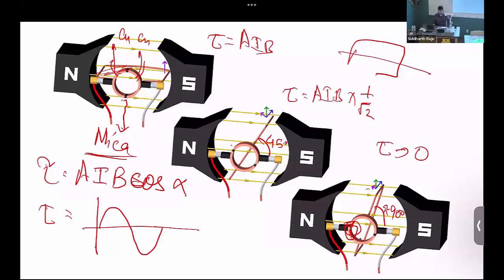So this torque profile, the way I've written it, it would appear as if it's going to look sinusoidal, right? Or cosine, phase shifted by 90 degrees, where this is the alpha angle. So is that correct though? This would be problematic, right? If I have a rotational element and if I create a torque that's sinusoidally varying, the net torque is going to be 0. Average of a sinusoid is 0. There is no net torque acting on the system.